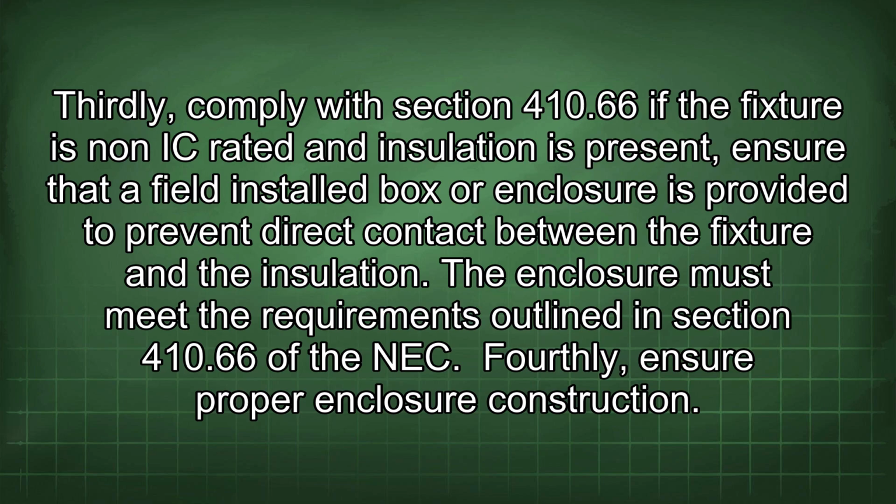Thirdly, comply with Section 410.66 if the fixture is non-IC rated and insulation is present. Ensure that a field-installed box or enclosure is provided to prevent direct contact between the fixture and the insulation. The enclosure must meet the requirements outlined in Section 410.66 of the NEC. Fourthly, ensure proper enclosure construction.